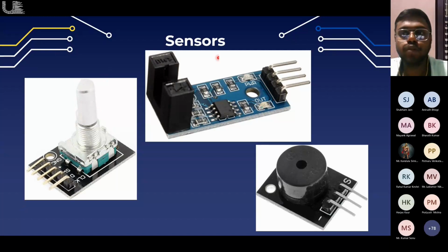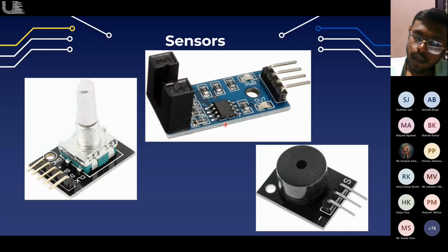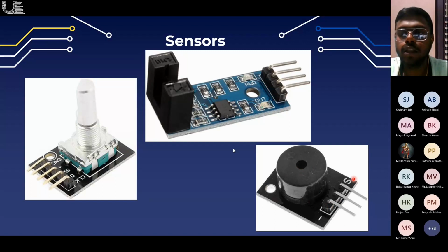This is a passive piezo buzzer module. If you want to control the frequency of the tone from the buzzer, then we use the passive buzzer module. We use it for generating a buzzer sound. The tones of this module range in frequency from 1.5 kilohertz to 2.5 kilohertz.